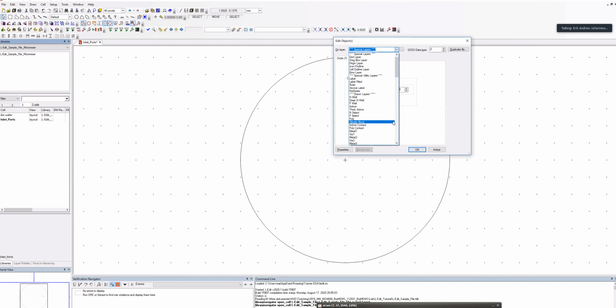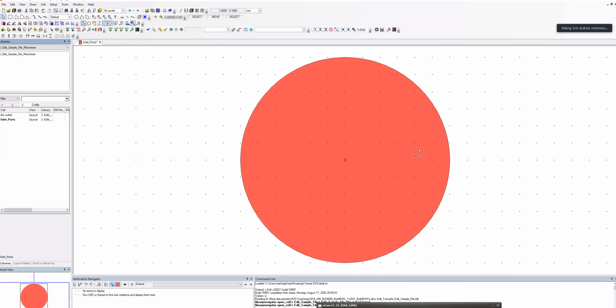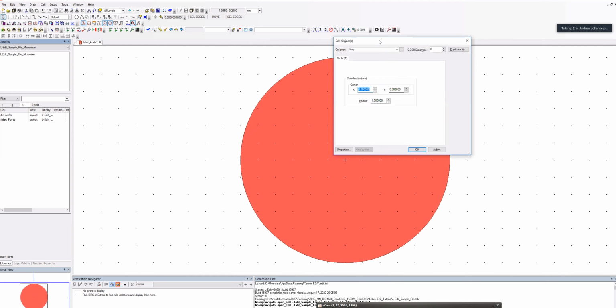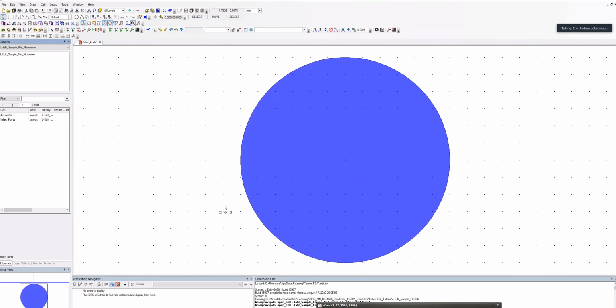We are only going to focus on one layer. You can just choose poly. Poly is normally used for polysilicon definition in microelectronics, but for us it doesn't really matter. We just need a layer that we define, and we know the design is on the same layer if it's going to be connected together on the mask at the very end. I tend to use these metal layers. I feel they are easy and quite visible also.